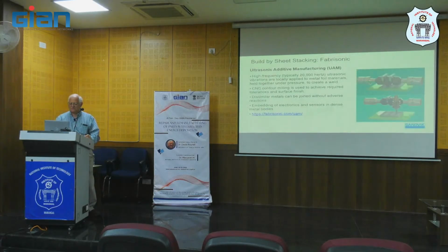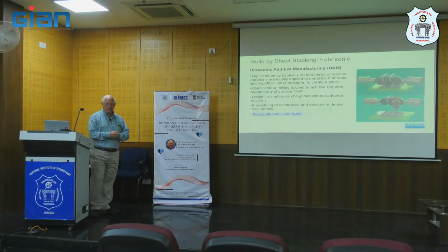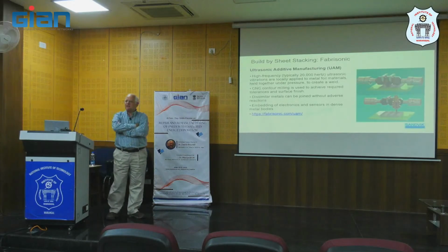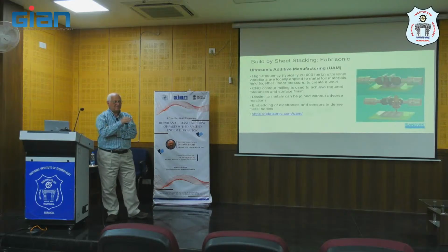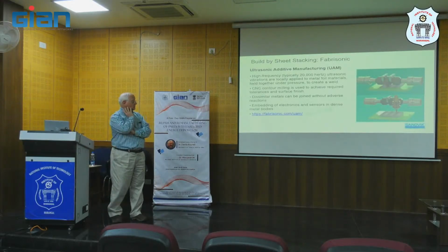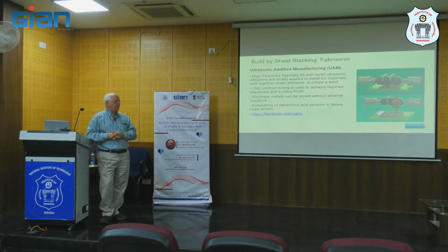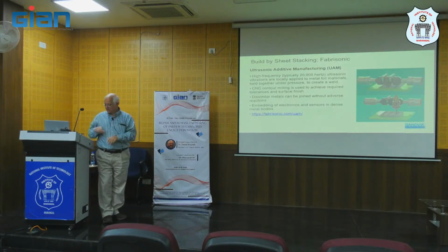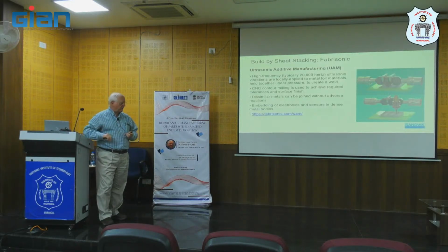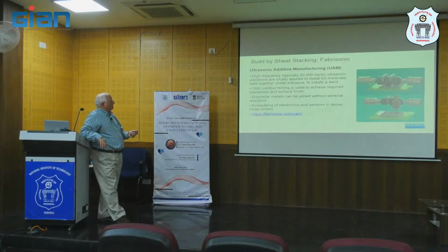So again, we have that, a little different. This is sheet lamination. It's neither powder bed fusion nor directed energy deposition. I thought I would show it. It's sort of a prime example of sheet lamination additive manufacturing. This is an ultrasonic additive manufacturing approach. This comes out of Columbus, Ohio. It's sort of a spin-off out of Ohio State University, I believe.